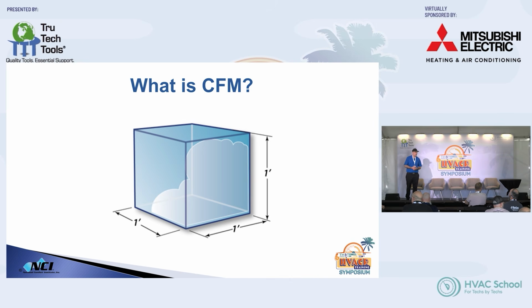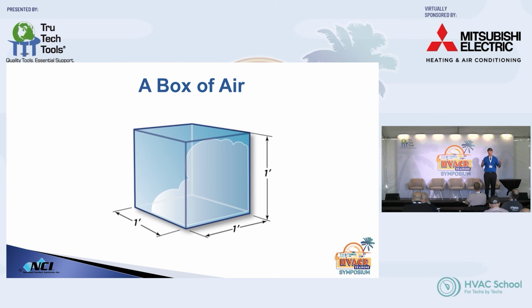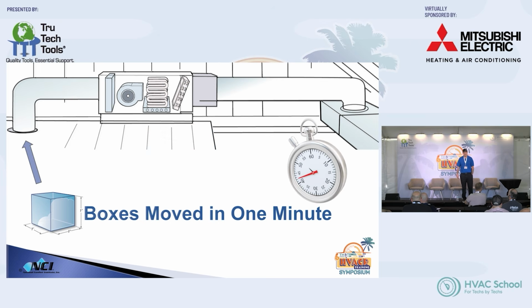Yep. So what is CFM? One cubic foot of air, right? It's a box of air. It's just a box. You guys know Ty Branneman, right? He did an awesome video where he's stacking boxes up. This is a cubic foot of air. You start thinking about how much air a blower motor has to move, it starts blowing your mind when you think about the weight of air, right? So a CFM is how many boxes you move in 1 minute.